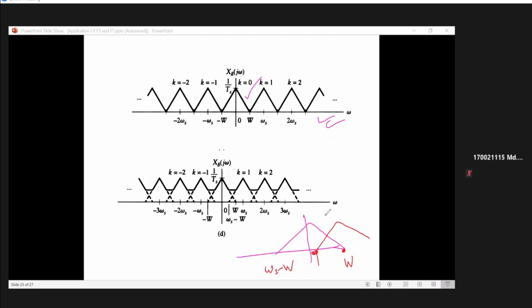If we put a line there, you will see this portion and that portion. Can you find the shape? Is it not that this portion is folded over in this portion? And that is what we call the folding frequency. That means at that frequency it will be folded over here, and one of these portions is actually unwanted. And that is the aliasing.